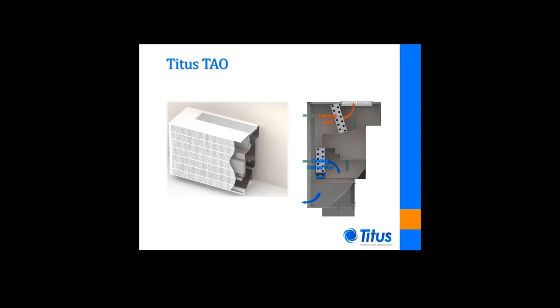The unit also consists of a ducted primary air plenum, several rows of nozzles which inject the plenum air into two separate induction sections, and separate mixing sections where induced air, room air, mixes with the primary air injected by the nozzles before being discharged to the classroom.